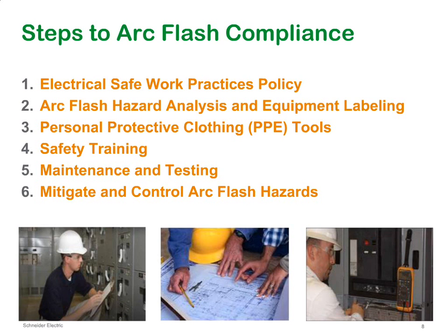Procedures need to be written that establish how to approach electrical equipment, how to safely do what is allowed on them, and also procedures need to be established about training of the workers, how they need to be trained, what training they need to receive, on what kind of criteria or selection, and all of these go into that safety policy. So if you don't have that safety policy, or if it's not up to date, if it hasn't been audited within the past 3 years, that's something that you would want to do first, because the NFPA 70E standard requires the safety policy to also be audited on a schedule not to exceed every 3 years.